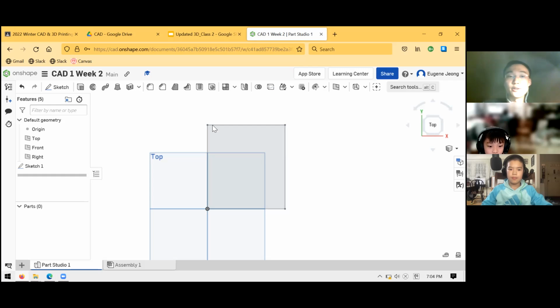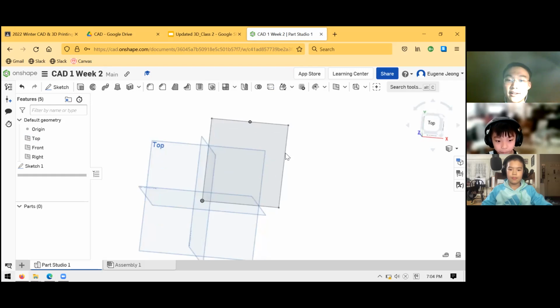And when I do that, now you'll see I'm no longer in the sketch workspace. If you go back to the toolbar, you can see the tools all changed into what it was before, things we haven't worked with yet, but they're not the familiar line and rectangle and circle options anymore. It's just these other things. And you can see also that the sketch has turned into a grayed out collection of lines instead of the blue and black lines that you saw in the sketch workspace.